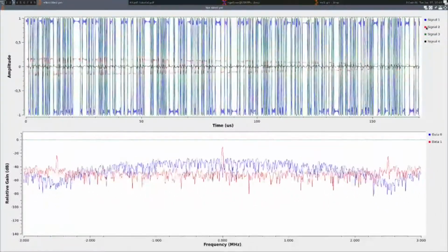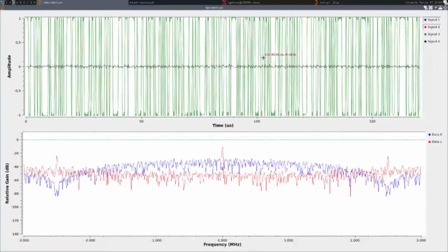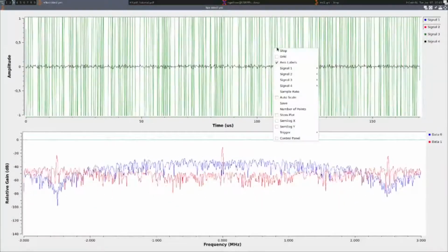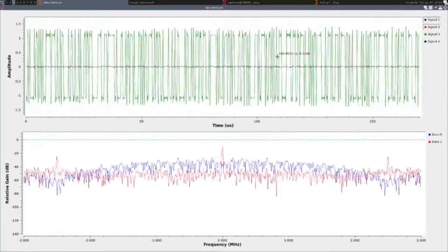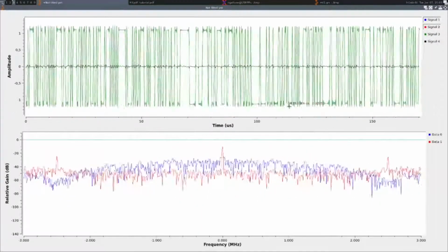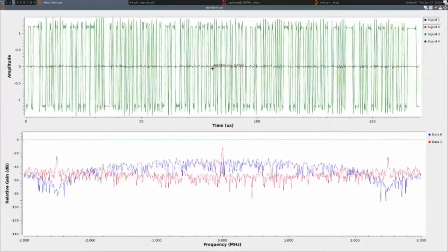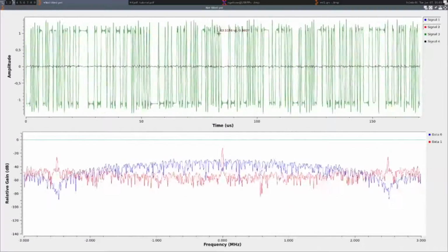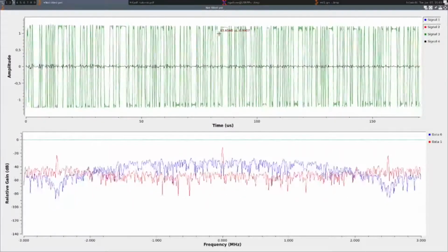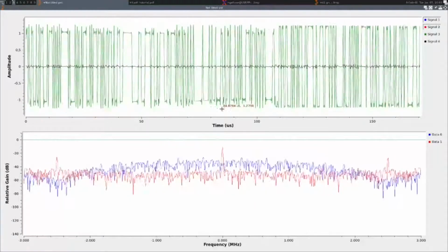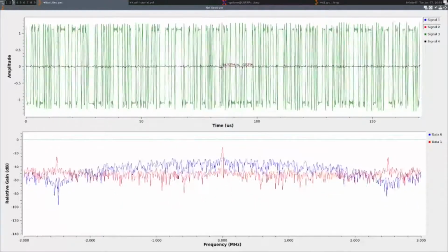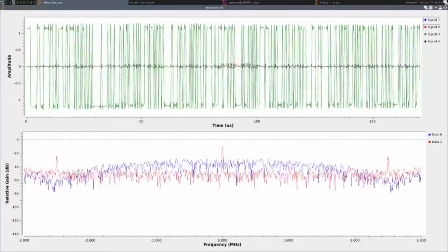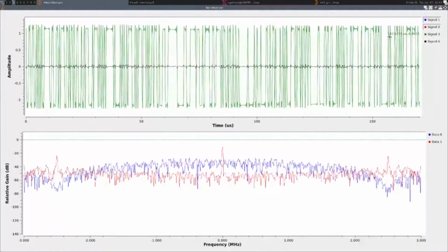But if you look after the Costas loop correction, you see here that now the imaginary component has been cancelled and only the real part is fluctuating, because cosine of 0 is 1, cosine of pi is -1, and sine of 0 or pi is 0. So here we have a proper lock of the Costas loop.